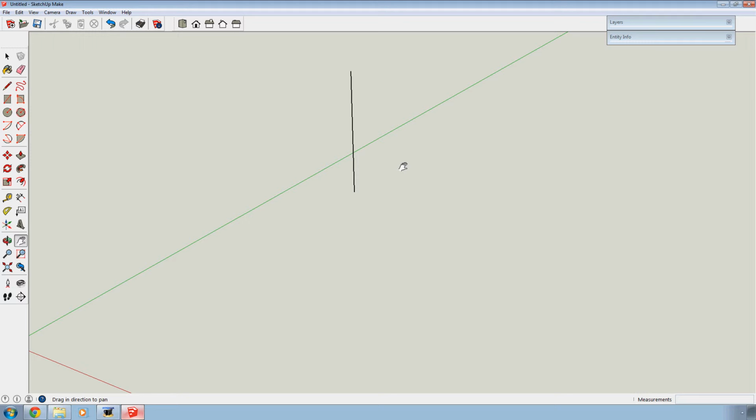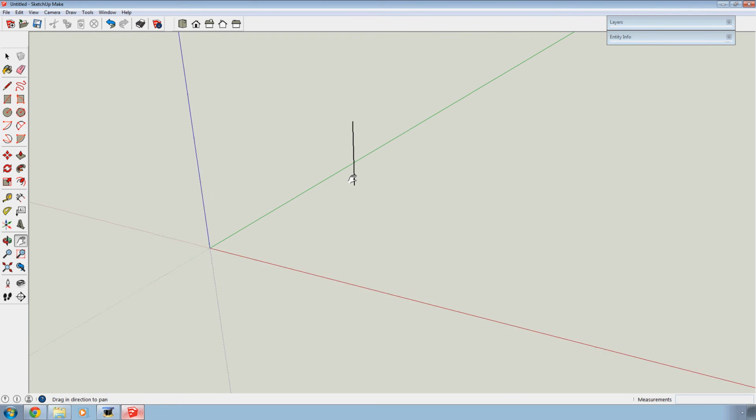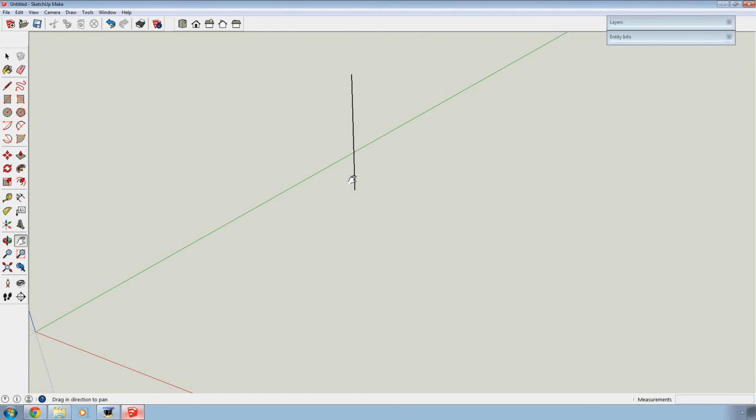The other way of getting at the pan tool: the mouse, if you're using a mouse, and you should be using a mouse, should have a scroll wheel, which is very useful for zooming in and out. As I roll it forward I move in, roll it back to move out. And if I click down on the scroll wheel, I'll get the orbit tool.